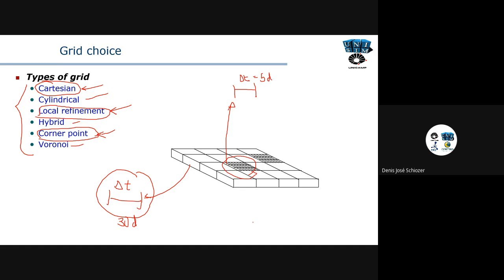So now that you can use the simulators, for example, the IMEX, you can try to put local refinement in all the wells, and sometimes instead of 1 hour, you run your simulation in 2 hours, for example. So you have to be very careful when you use these local refinements and these complex geometries, because the simulation time will increase a lot, okay?